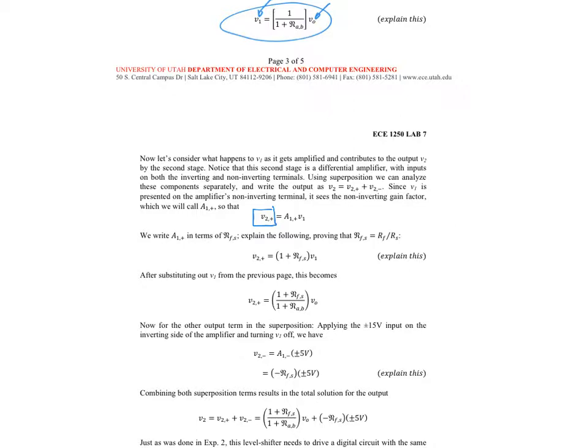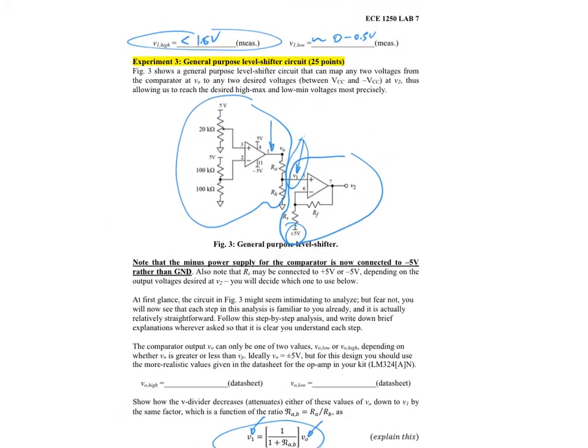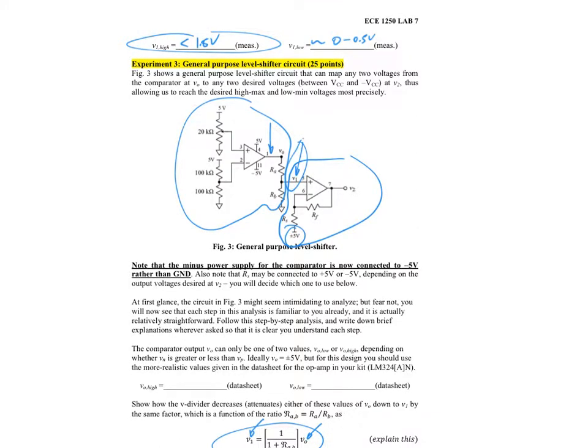So we know that. Now take that, and for the positive, the component of the amplifier, the final stage, due to the positive input, is the gain on that times its input. Alright, so the input is V1. It gets a gain. So V2 here is V2 plus V2 minus. V2 plus is the component of the output due to V1, the portion that's on the positive, the non-inverting input, and V2 minus is the component due to that guy there.